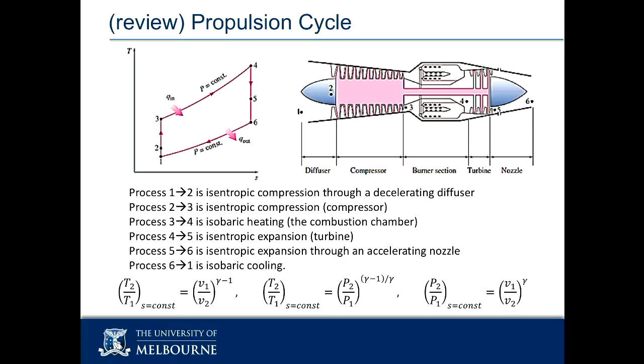So they make our life a little bit easier, because the very first thing is someone tells you, I've got a gas turbine that's sitting in the outside world, so it's sucking in air at 1 atmosphere and 27 degrees, and it's got a compression ratio of 35. Tell me the temperature at the end of the compressor. Adiabatic process, isentropic adiabatic process. I grab this guy. You've told me it's air, and so I've got gamma, because gamma is a property of the air. I can then solve for the temperature.